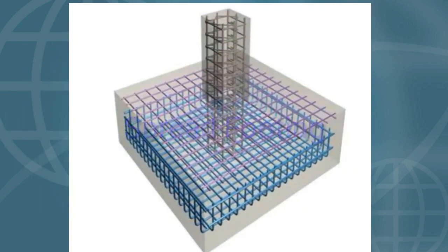Okay, next one is spread footings. A spread is given under the base of the foundation so that the load of the structure is distributed on a wide area of the soil in such a way that the safe bearing capacity of the soil is not exceeded. So this type of footing we are calling spread footing.